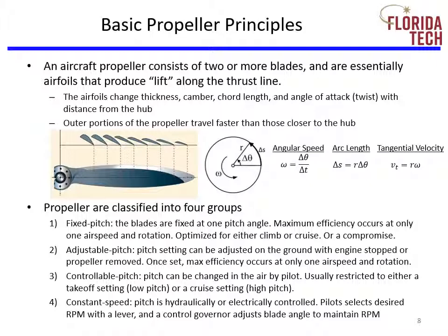Now we'll examine what creates the thrust for the airplane to fly. As the combustion occurs in the cylinders, the pistons rotate the crankshaft, which directly drives the propeller. The propeller is actually twisted. This is simply to create equal thrust across the propeller blade. Since the propeller rotates about its hub or center, the further the propeller extends out from the hub, the faster the tangential velocity. To create equal force throughout, the manufacturers twist the blade.